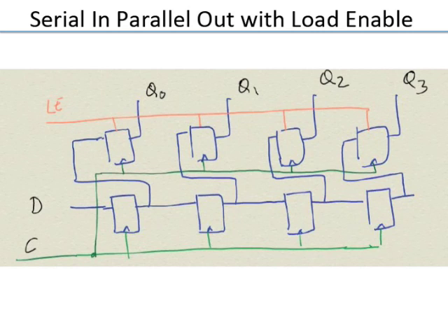So the supply band is always closed. Pardon? The supply band means the signals of flip flops. Lower level flip flops are always stored according to the bits entering the flip flops. Only the upper level flip flops will be changing with the enable. That is right. The lower one will not change with the enable because there is no enable here, but the upper one will change with the enable. Yes. But it doesn't change the activity factor for the lower one.